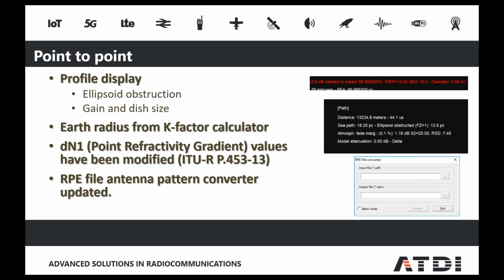So essentially, when you have, say, your 3 or 4 dBs below what you're required for your availability target, 4 nines, for example, then it would say, okay, I might need 4 or 5 dBs in terms of additional gain required, and this is just going to make a suggestion in terms of the size of the dish related to that.